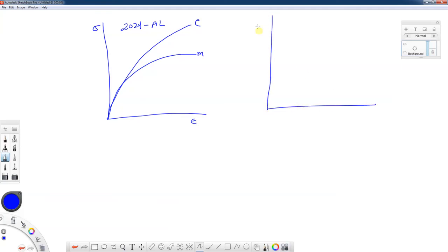And I realize there's various heat treatments and things like that, but this is just an example of what can happen. Here's maybe a stainless steel. It's a very strong material, has a kind of a high slope to it in the plastic range. But if we cycle it, we may end up with a softer material behavior. And in general terms, we can express this in terms of the strain hardening exponent, the monotonic strain hardening exponent.